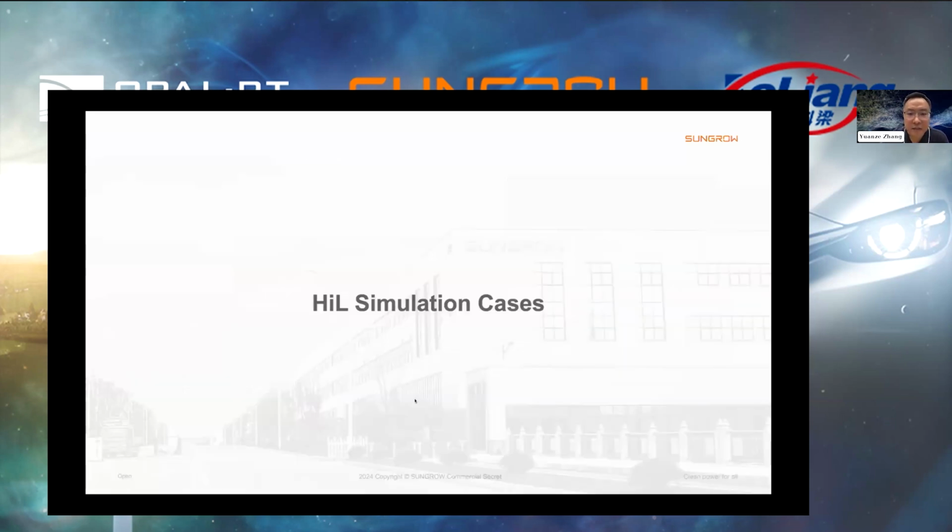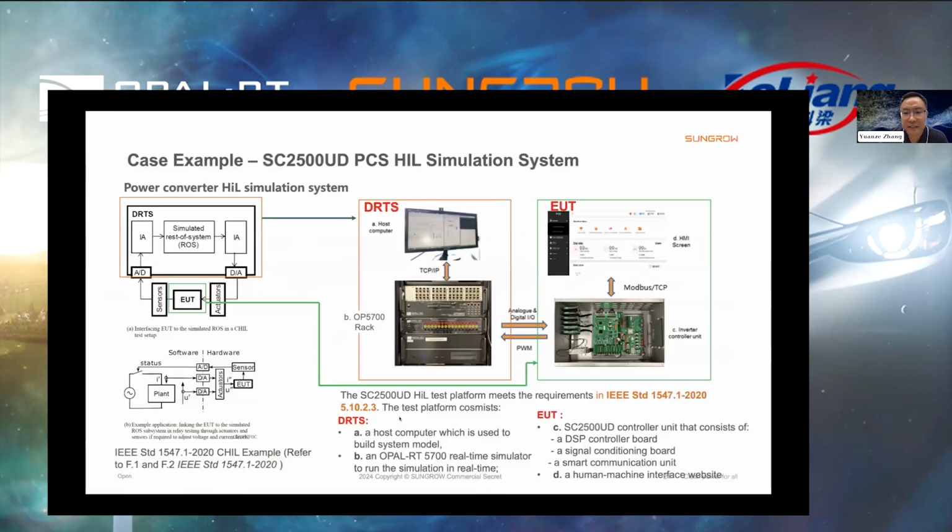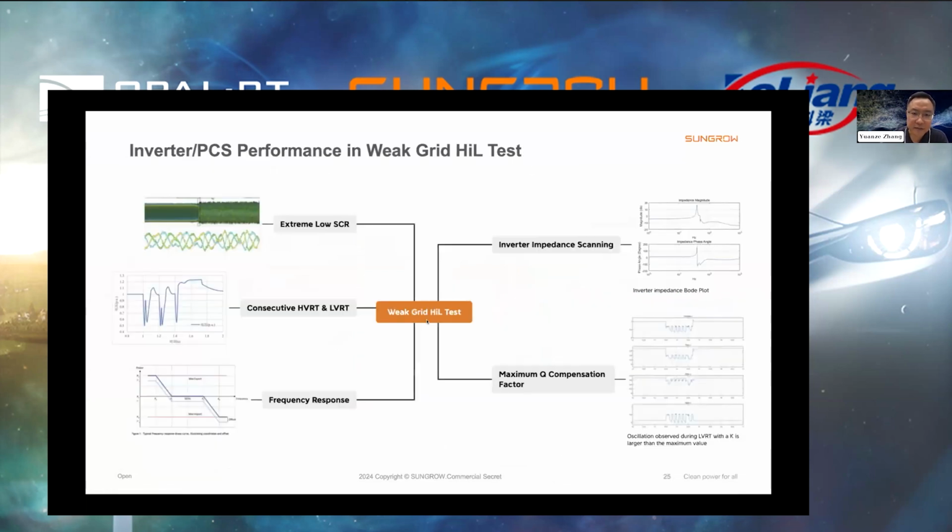So here I'm gonna share some simulation cases that we've done previously. The first one is the simplest, just one inverter controller connected to one real-time simulator to run all kinds of grid connection tests. So we built a big grid HIL test platform, so we can test both grid forming and grid following control strategies. We can test their extreme low SCR condition, like we push them to the limit to see what's the lowest SCR the inverter can work.